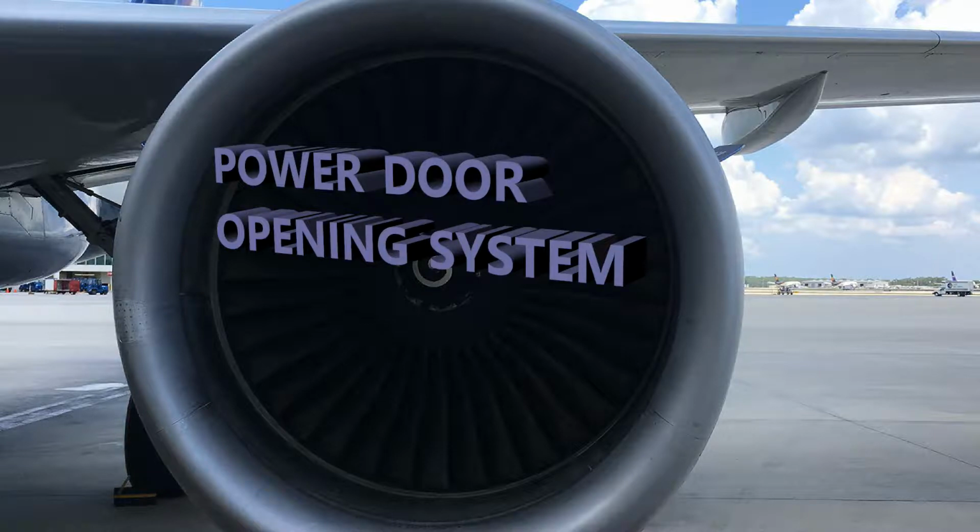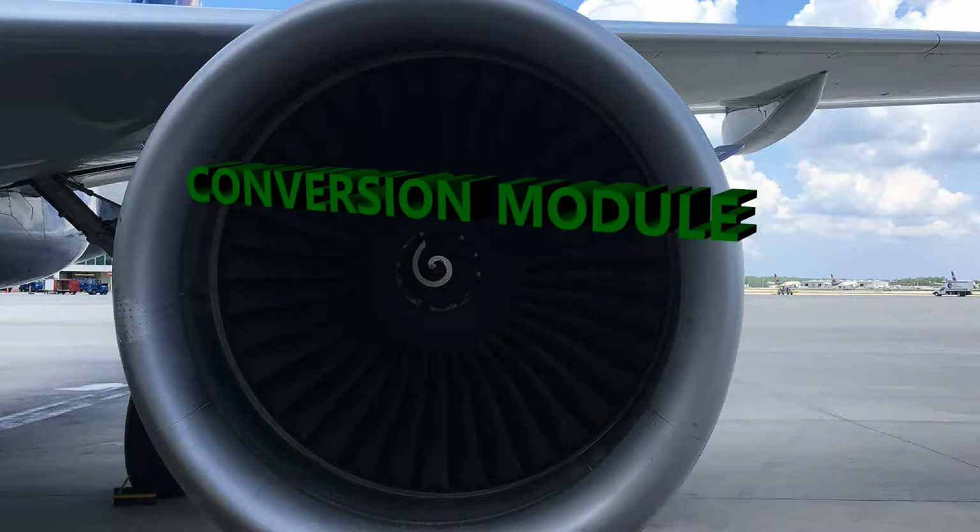As far as your electronics goes with all of this, obviously we're talking electrical. We've got these components here. You have a conversion module that's here. So when a control switch is pushed and held, you're going to have that logic module in the power pack send a signal to a conversion module. Okay, that's also using the fire protection system. But that CM, which is your conversion module, is going to send that information to the engine interface function, which is going to go to another computer. I know it's computer to computer to computer, right? But that's just how it goes.